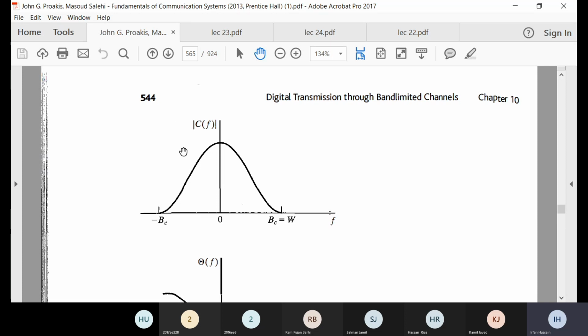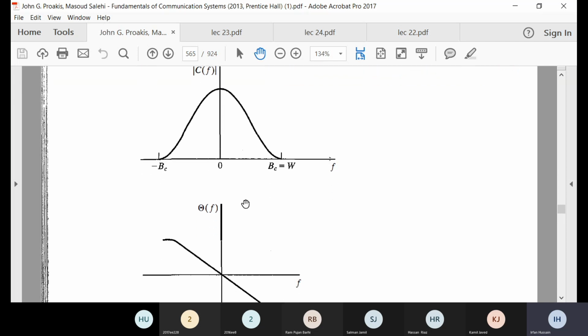So in this case, you can see that the channel response is conjugate symmetric, and so this means you can see both the amplitude and the phase, and you have the symmetry here. Because conjugate symmetric means that the Fourier values at the positive and negative frequencies are the same in magnitude, but in phase, one is plus j, the other is minus j.